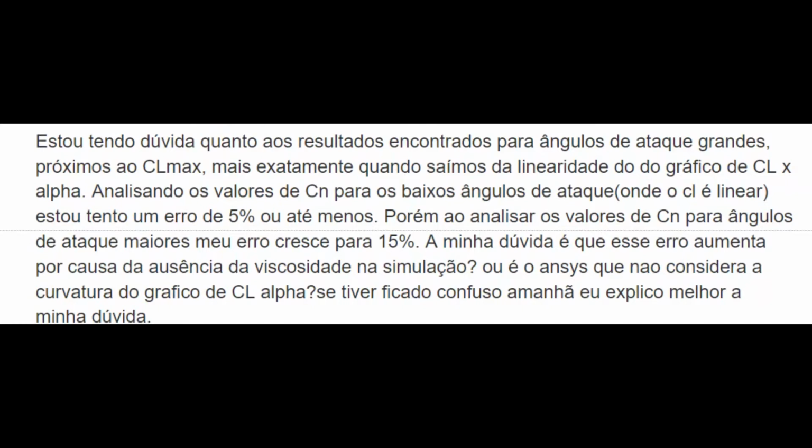And another thing, you ask us to include the convergence plots, which are the residual plots. Should we also include them for each angle? Could be nice, could be nice. For small angles, it's practically the same. And for the stall condition, it will be different because the flow separation starts to happen. But if you can put it for every simulation, there are only 5 cases, and you can put 5 small plots.